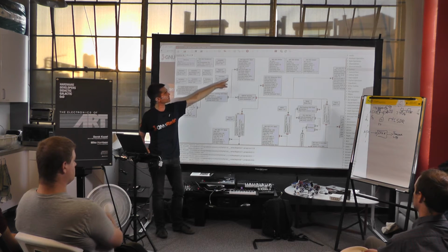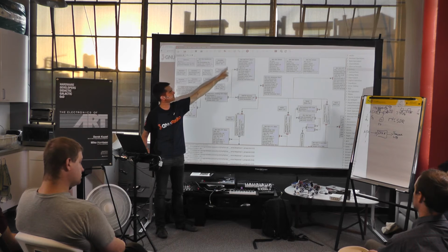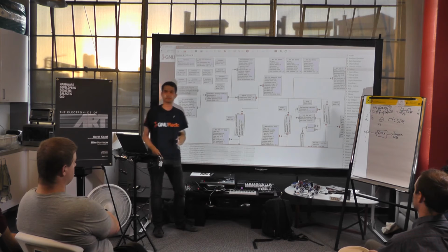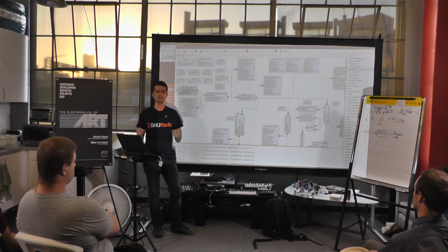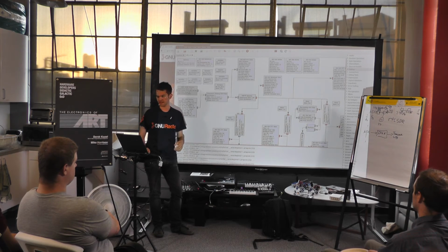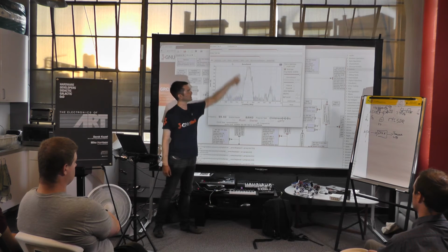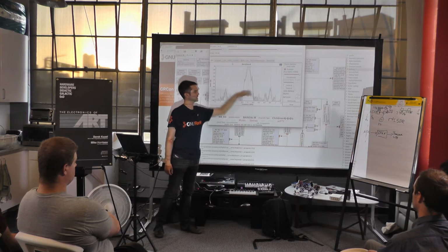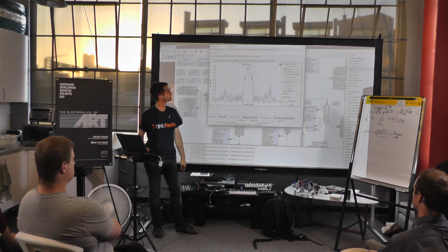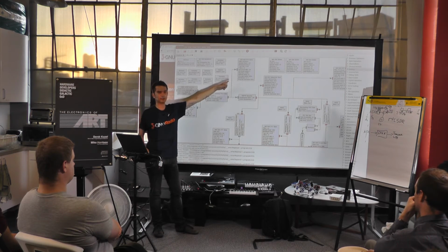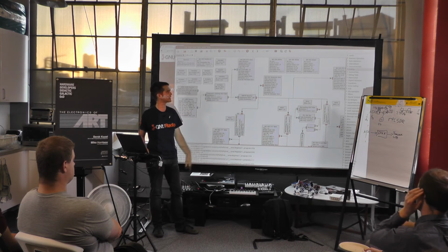The first screen that we were looking at here, title is Baseband. This is a GUI, fast Fourier transform sink. So the fast Fourier transform is a mathematical operation that takes this oscilloscope data that we're essentially getting, the time data, and it translates it into the frequency domain so that we get a plot that looks like this. So we can see the energy at different frequencies, and then it's changing over time. And it's as simple as just dragging down these three blocks, and you would be seeing that same frequency data.